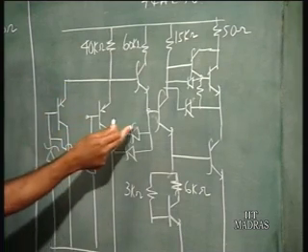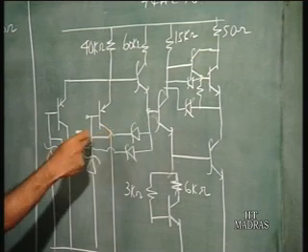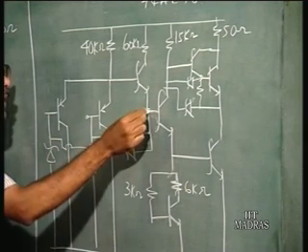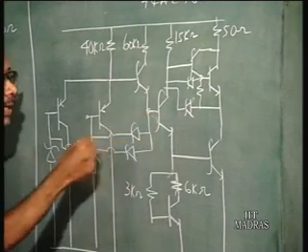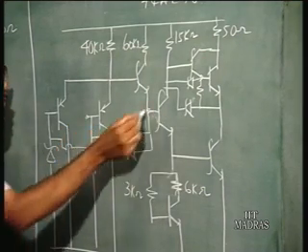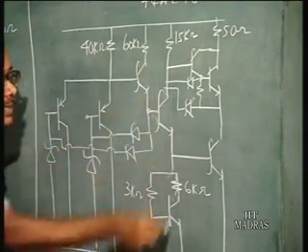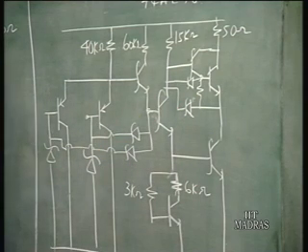Okay, and together with that, these additional diodes have been introduced, so that they have a direct connection to this point also. So that when any input goes low, this transistor here, which is basically the phase splitter part that we have been talking of, can switch off faster. So that is the circuit modification in the ALS series, 74 ALS.